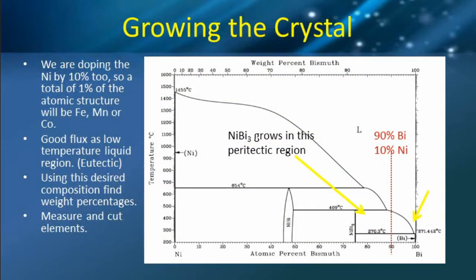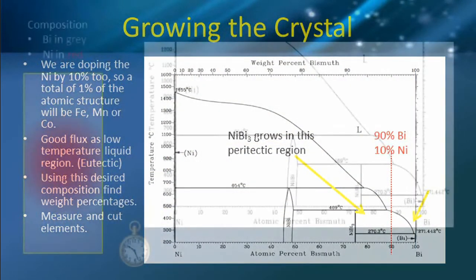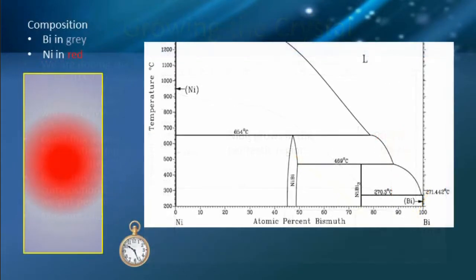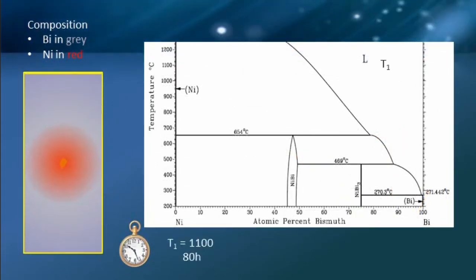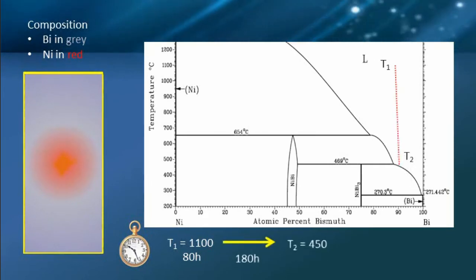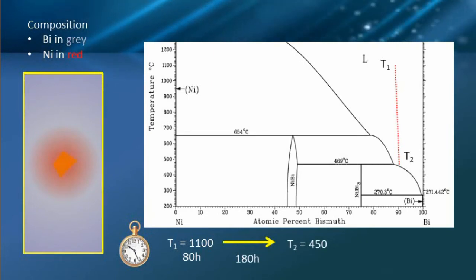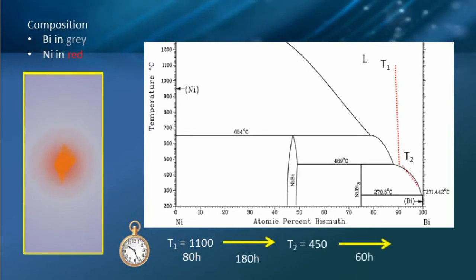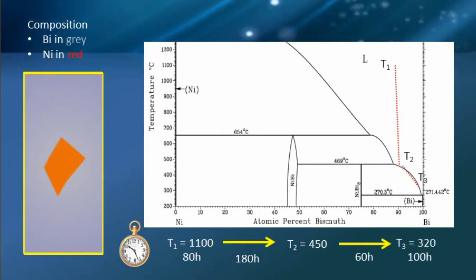It is important to choose an optimal temperature profile. This should give maximum time for crystal growth to avoid multiple nucleations. However, other important periods must be determined, initially to allow for homogeneity of the liquid, at the end to allow time to pull the crystals out. So, as our crystal forms, the bismuth flux increases. This excess can then be decanted using a centrifuge.